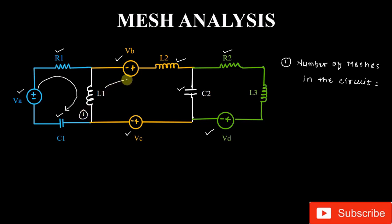Similarly, this is also another closed path, which I will number 2. This will be my second loop. Similarly, here is again one of the loops, and this will be the third. We can say that in this network we have a total of 3 meshes. So it is very easy to find how many meshes or loops are in the circuit. Now according to the procedure, what is our second step? The second step is to assign the current to each mesh, with the direction.